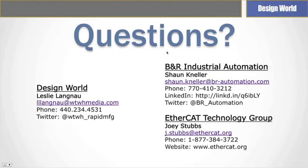We also have a diagnostic feature which works across the PowerLink, gives you diagnostic information on the PowerLink. So all of our SG4 controllers support this feature. You can just connect up with a standard PC, and you can then do diagnostics across the PowerLink through that. Don't need any special code. It's all Internet Explorer.